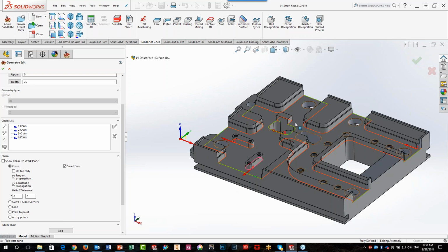And for the semi-open, it marked whatever was open and what's closed. And you'll also note that it did not choose any of the holes or through pockets as shown over here. So creating a geometry now is very simple. One click, you have all your open edges, you have all your studs, and it ignores all the holes as well. Now, these are also regular chain geometries.